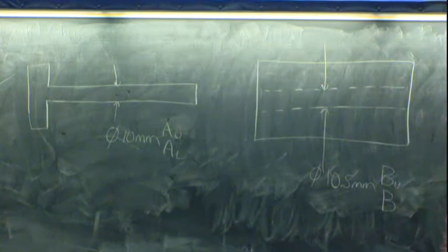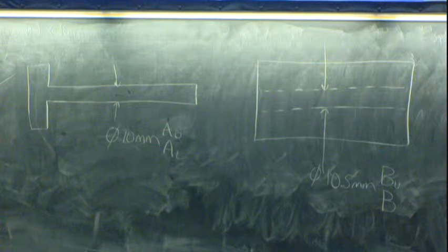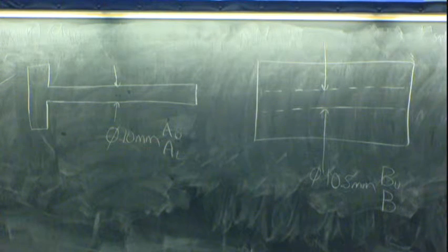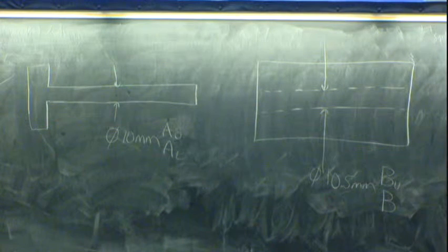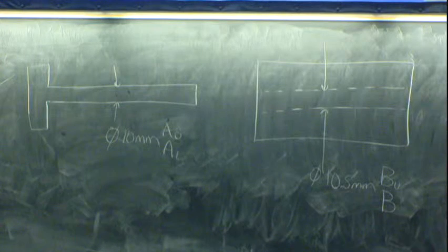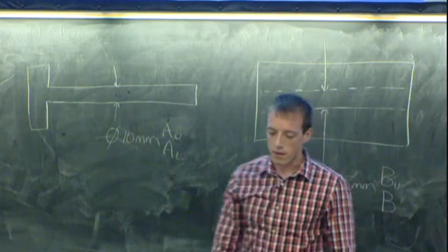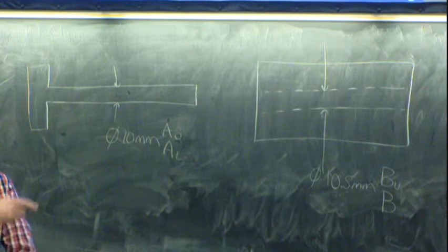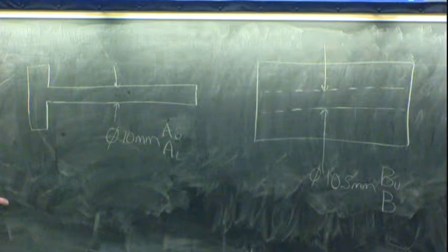And we're going to consider these at something called maximum and least material conditions. Remember to call it least material, not minimum material, because minimum and maximum both start with M, so when you make an acronym, that's kind of hard to remember. So if we call it least, we can call it LMC. So at these two conditions, they set the outer bounds of where the part will be allowed to be.